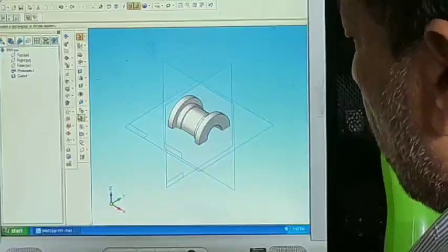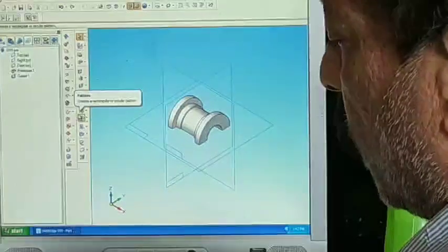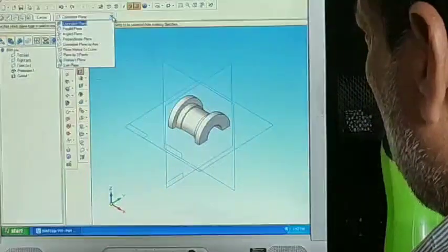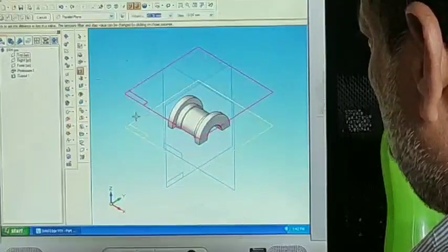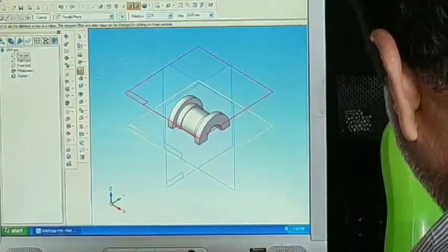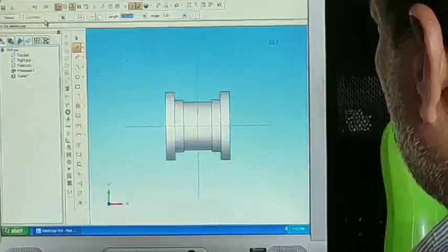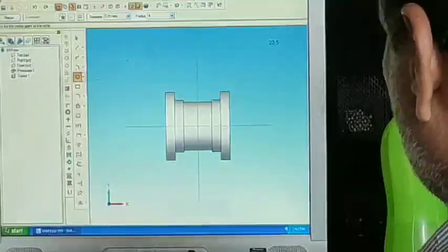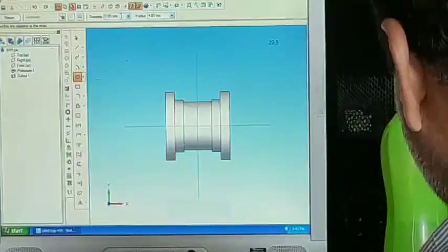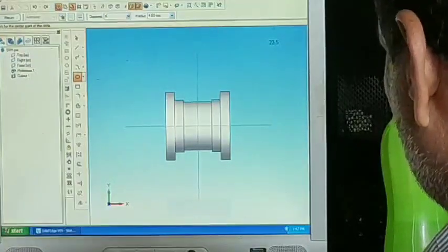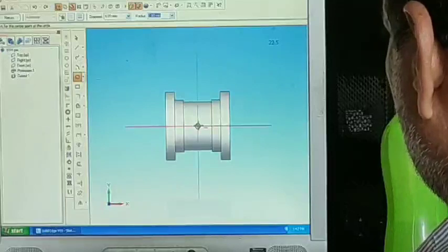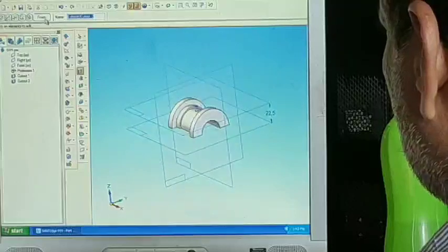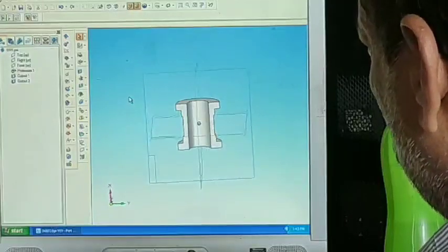So now I want to make a hole there. So that is bearing bottom half, hole diameter is 4 mm. Same thing, cut out. Again go to parallel plane, parallel to XY plane. 22.5 is the height. So go to circle command. So the diameter is of 4 mm. Place it in the center. Return through all downwards. You observe here there is a hole.